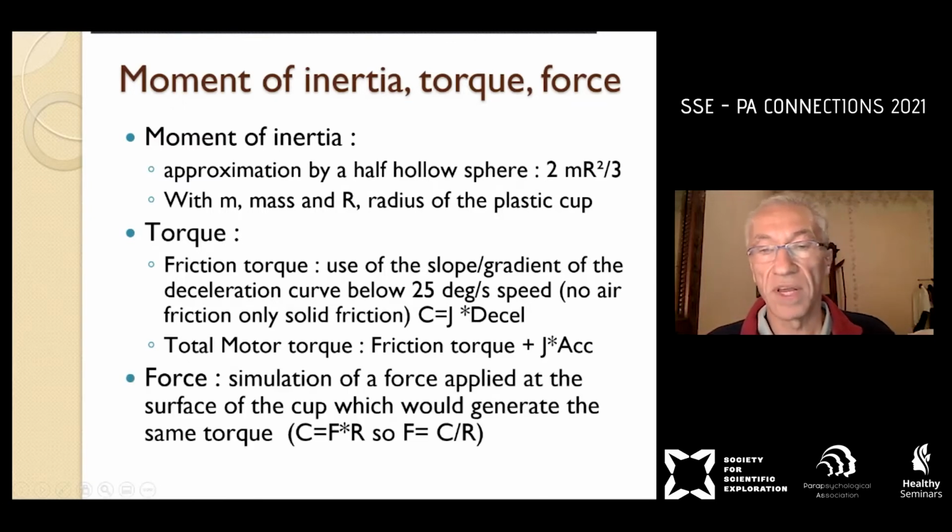And if we want to have an idea about the force implied, we can say that the torque is created by a force applying on the radius, on the surface of the target, so at the radius, and so the force is torque divided by the radius. So let's go to the first video you see.